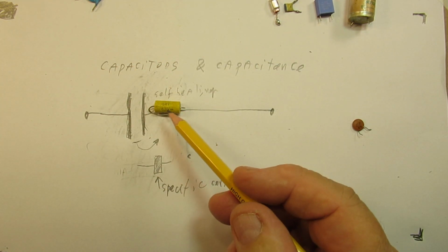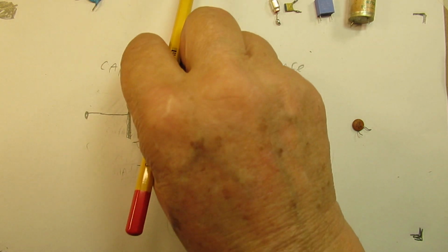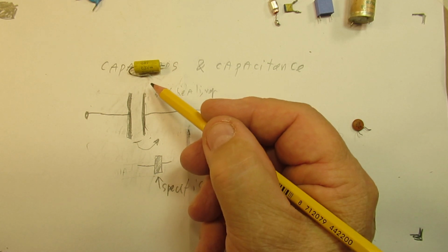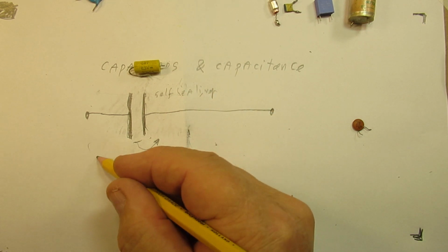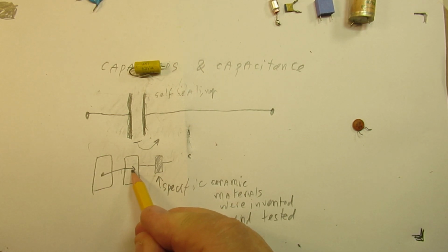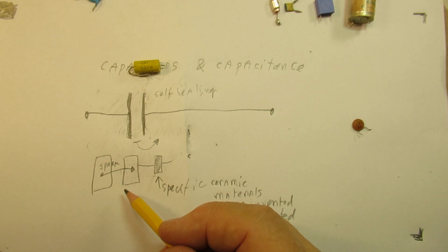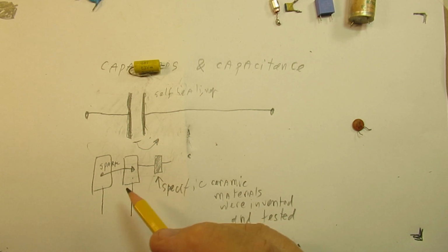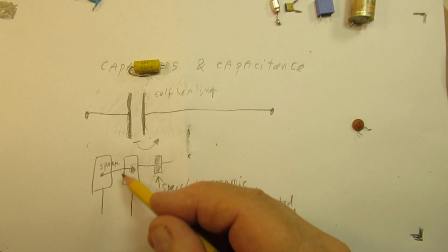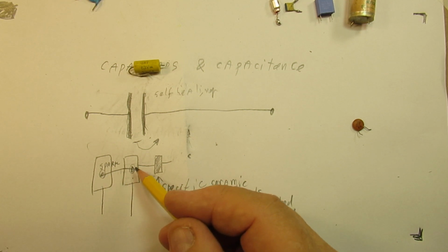It means that when there is a too high voltage on certain parts inside the dielectric, and in that case it could be plastic or other high quality plastics, we have here a layer and another layer in that capacitor, and when there is a voltage drop, a spark, between one plate and the other plate, the capacitor heals itself by repairing these two places over which there was sparking.